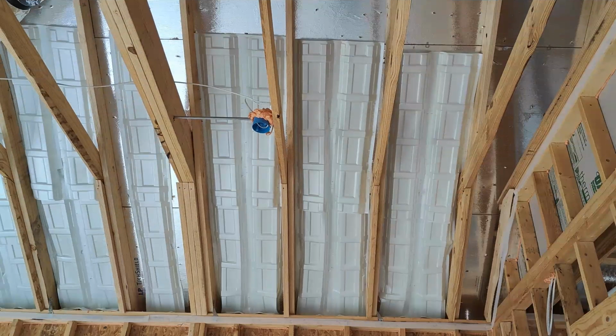So here we see a cathedral vaulted ceiling that has baffles that are correctly installed that extend well beyond the depth of the blown attic insulation. For the most part, they're fully filling each cavity. There's one to the left where they broke it in half and just used half of it. With this type of baffling, you can't use 3/4 of it because, I mean, I guess you could, it just makes it more difficult to staple in. So they just break them in half. It really should be fully filling that cavity. This reduces wind washing of the insulation, which can mean two different things.